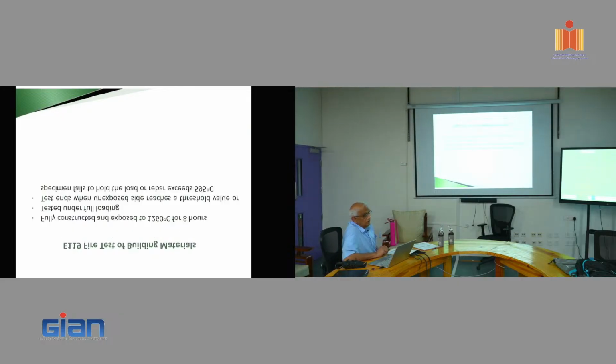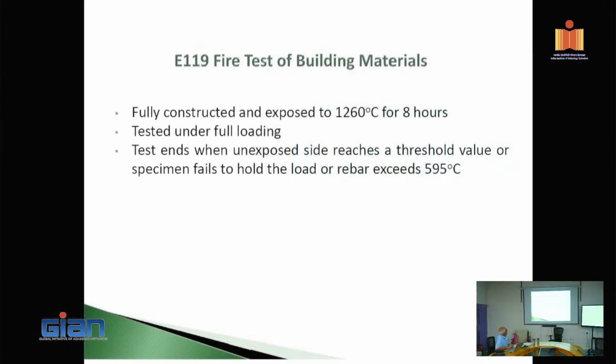There we go. E119 test, corner fire test. Fully constructed and exposed to 1260 C for 8 hours. That's called a corner test. How long, how much will it survive? What is the remaining strength? Those are the issues. Test ends when the unexposed side reaches a threshold value, and that number is given.